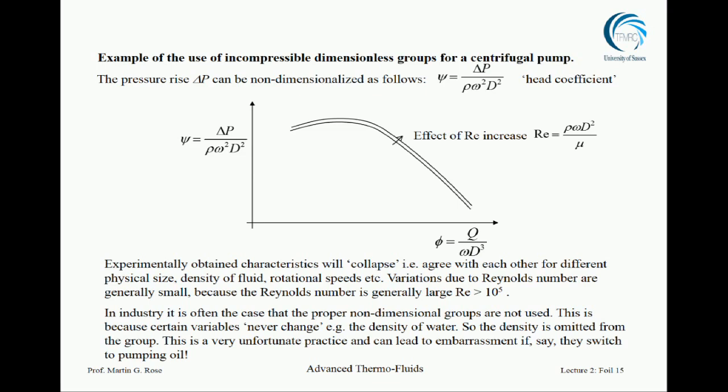And the reason for this ultimately is because the Reynolds number in almost all the machines you'll ever meet is high. We have high levels of Reynolds number, which means that the flow rapidly becomes turbulent. It's unstable from day one, and the consequence is that all the designs are turbulent, so the change of performance between them is very small. And we end up with almost the same characteristic, ignoring Reynolds number.